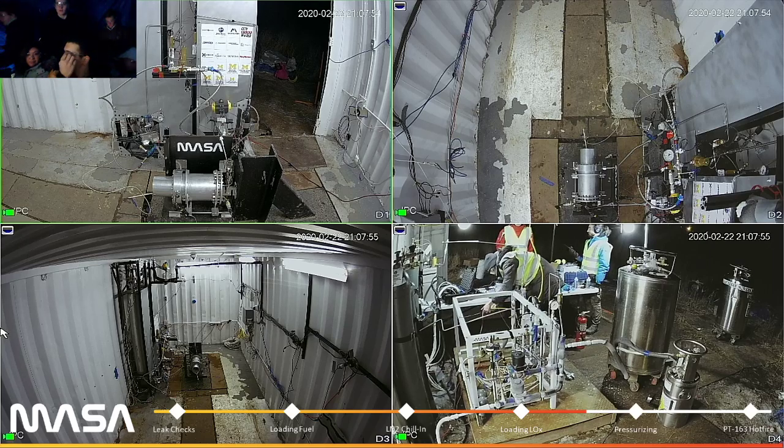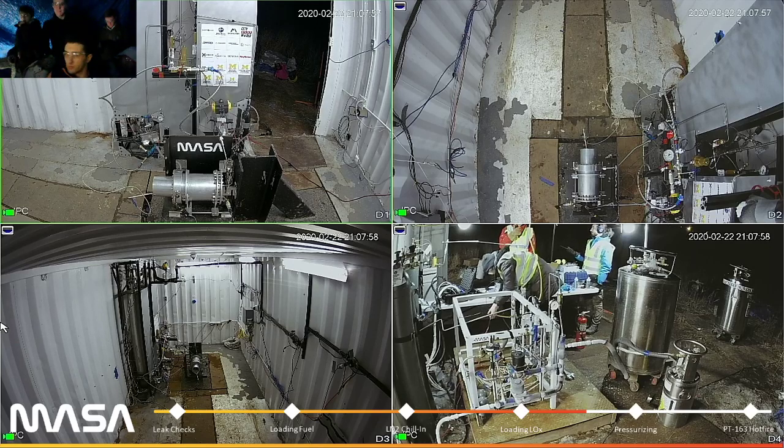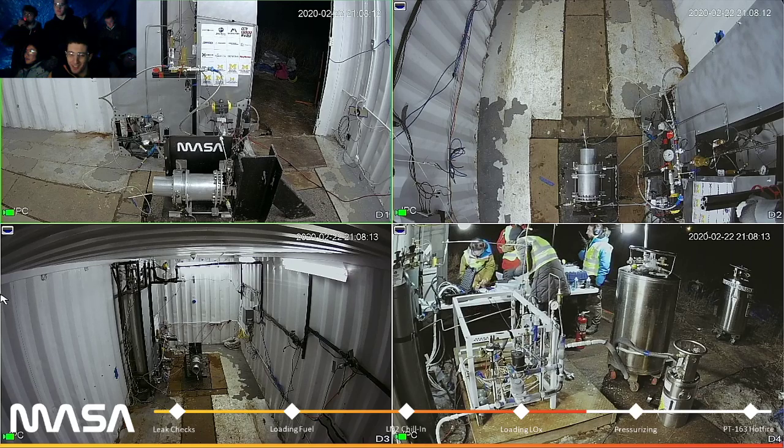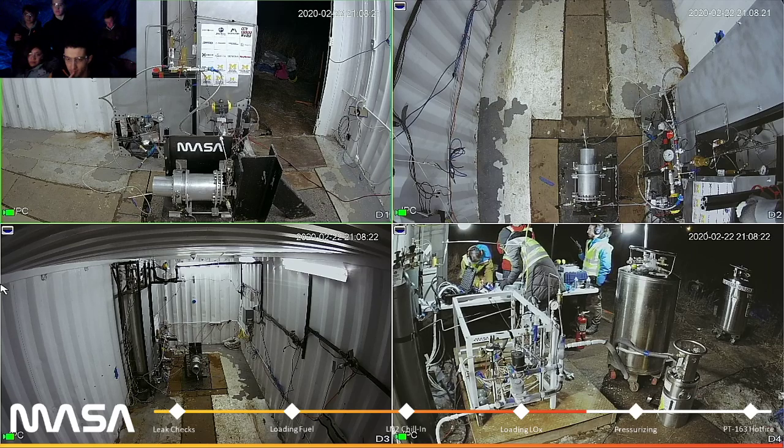Oh, you're charging it down there? Yeah, LiPo balance, 5 amps, 3 cells. Should we balance it? The mode is LiPo balance. Hold down the enter button. Jeff is gonna know how to do it. I think that charging it without balancing will be faster. The charger normally supplies 2 amps, balance supplies 5 amps if I'm correct. You can cycle through and check though. Just let Jeff do it. I think we should just do it the same way we normally do it. During LOX-fill, we'll have enough time to get up to probably around 11.6, 11.8, and we should be good to go from there.